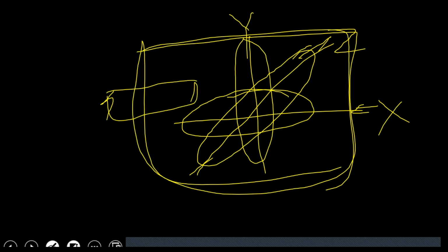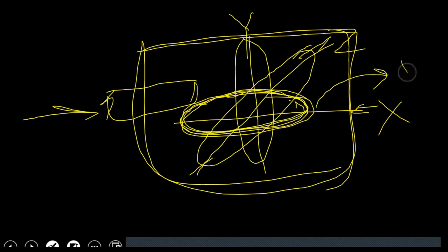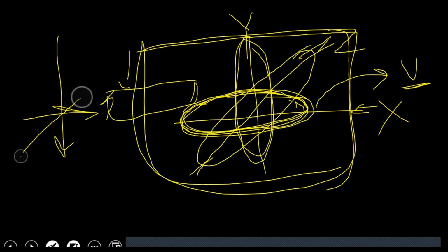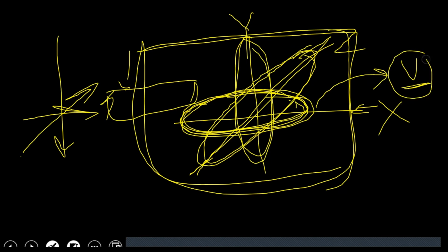So on this cutting tool, if there is a horizontal force, this horizontal transducer comes into picture, deformation occurs in that horizontal transducer, and you will get the voltage generated. If a vertical force acts on the cutting tool, this vertical transducer will respond, and you will get voltage potential. Similarly, in the third direction, if force acts, another transducer comes into picture, and you will get the potential difference.